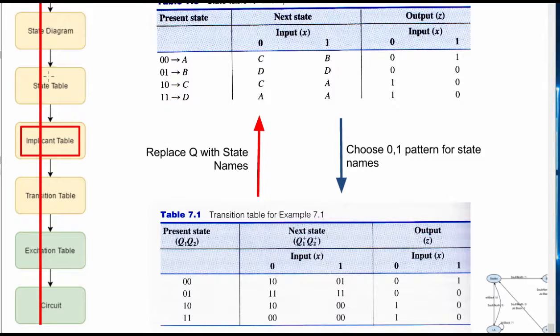As we go down, information is discarded. We discovered when we went down from the transition table to the excitation table, there were don't cares that don't show up when we reverse engineer it. Now we're going to uncover even more significant stuff that's missing, that we can never know, reverse engineering it. Now, in reality, these states have names, like names of cities or something like that. But we're just saying A, B, C, D, just random context-less names. So here's how it works.